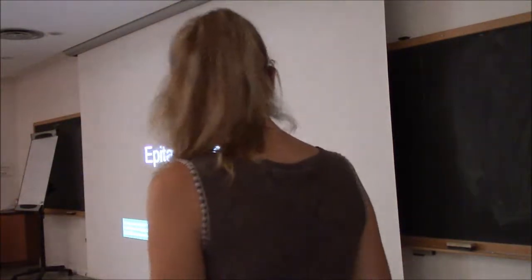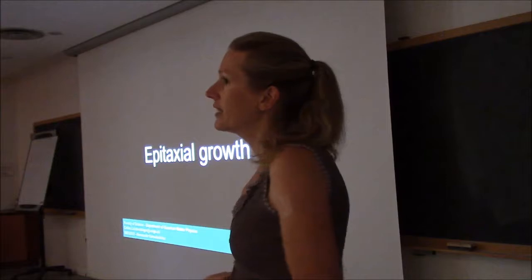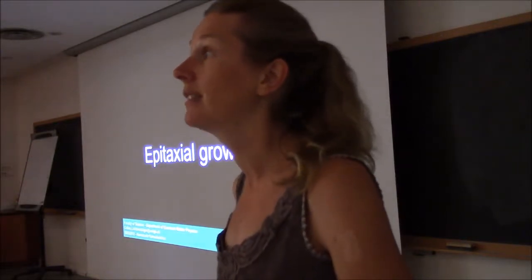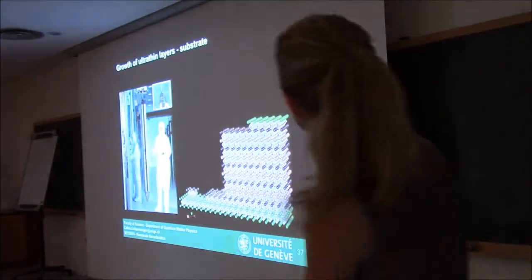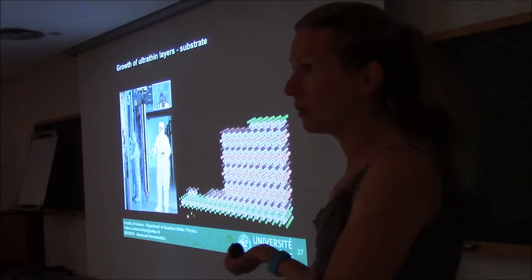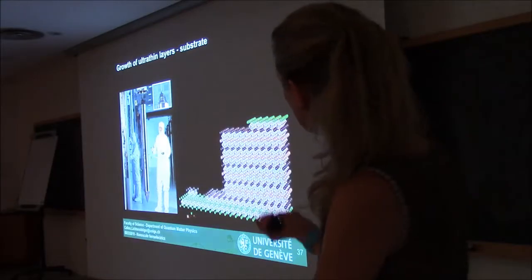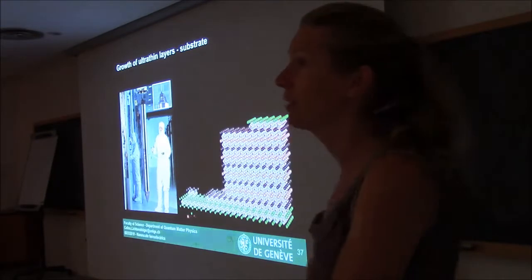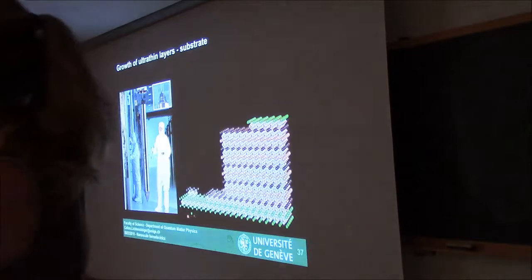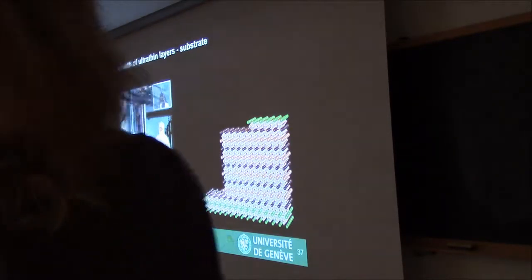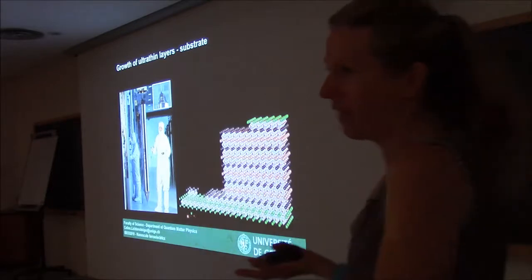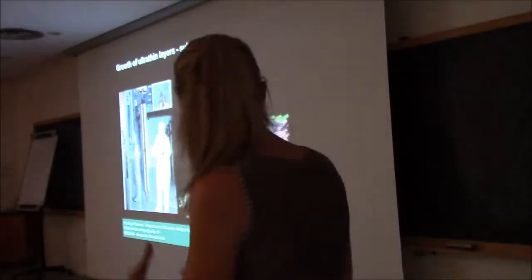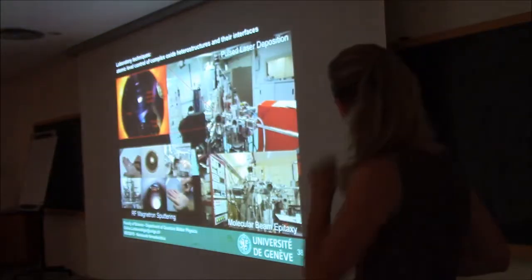So again, when we work with nanoscale ferroelectrics, I said that the strain is quite important. We are growing the materials using epitaxial growth, so I would like just to mention a few things about epitaxial growth. The importance of the substrate, we've seen before, but I want to show this very nice image. So this is a silicon growth of a crystal that produces the wafers. And of course, then, when we have a nice substrate, we want to be able to grow nicely the films on top of the substrate.